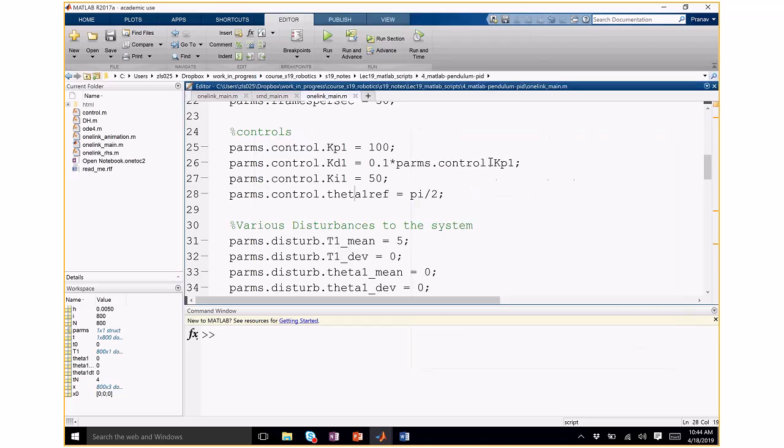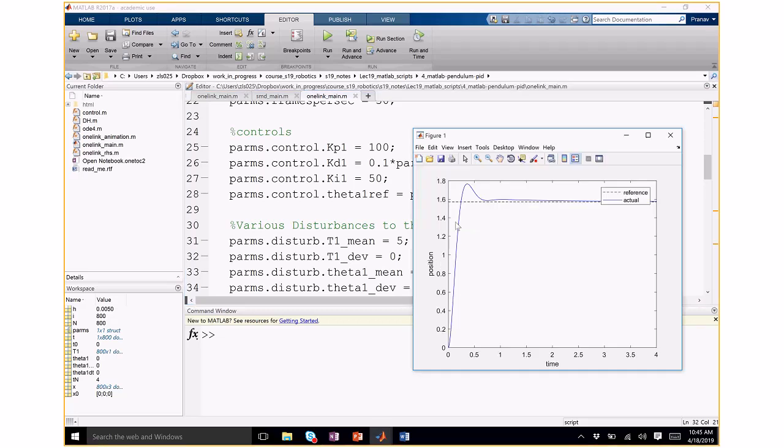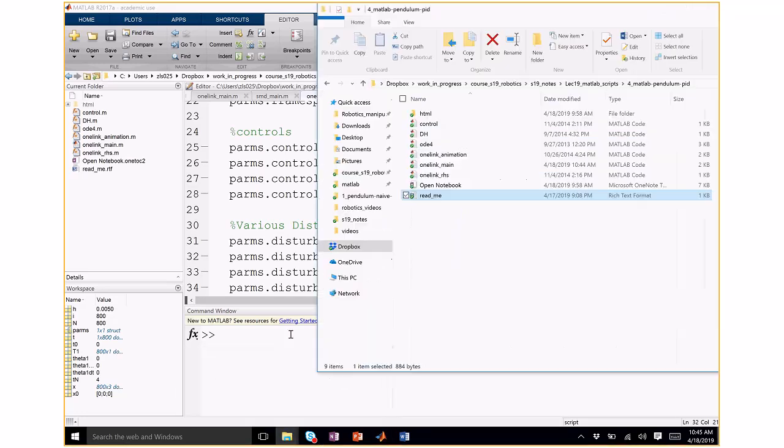So here you can see that the KD is not critically damped. Right here. In this case, what you notice is that there's an overshoot, but it settles down. So if you want both critical damping as well as zero steady state error, then you want the controller based on control partitioning, so you have critical damping. On top of that, you need to put a KI so that the steady state error is 0. I've not done the control partitioning part here, but you can do it. Okay, so that's it for today.